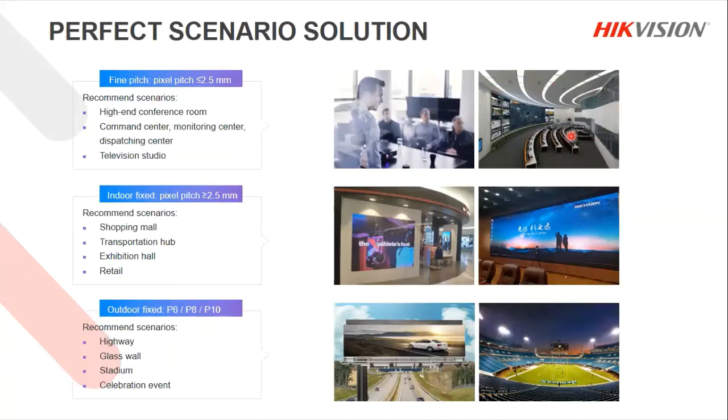Your wall rooms, you can see something like this here, your command centers, monitoring centers, and maybe even television studios. So we need a higher quality type of display, less than a 2.5 millimeter pixel pitch there. Indoor fixed, you can go slightly larger than 2.5 millimeter pixel pitches, and this is for your shopping centers, transport hubs, and exhibition halls, places where people are a little bit further away from these monitors than in a dedicated conference room.